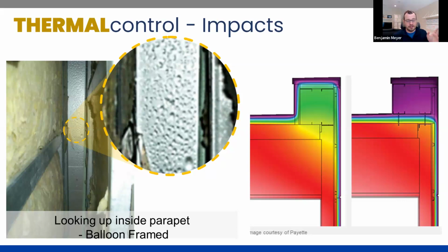So this is continuously insulated, but the more that parapet gets separated from the interior space, the more risk you have of moisture that is interior generated from pools, cooking, showers, what have you, hitting a cold surface and condensing back down. And the one, go ahead. Go ahead. I'm sorry, but having shown this slide to a number of contractors, the question of constructability always comes up, and I always toss it right back at them and say, well, what will it cost you to go back and fix it? Because you're really asking for a problem if you don't address it while you can see it.